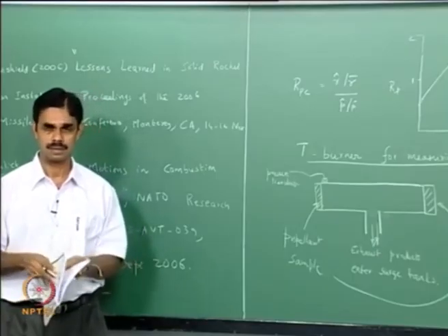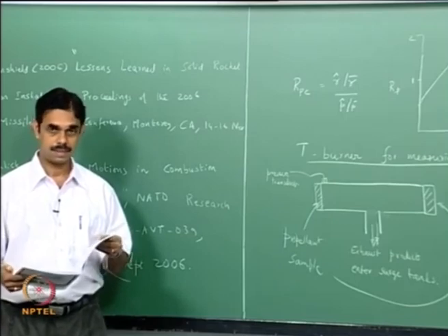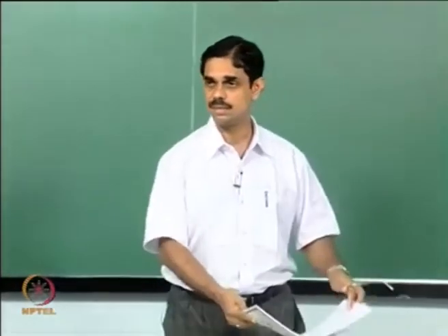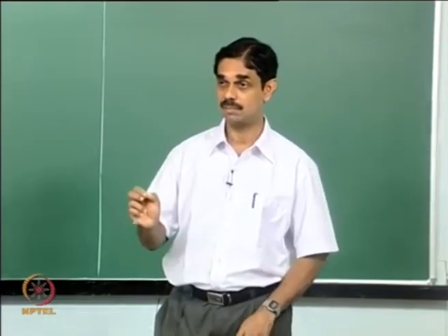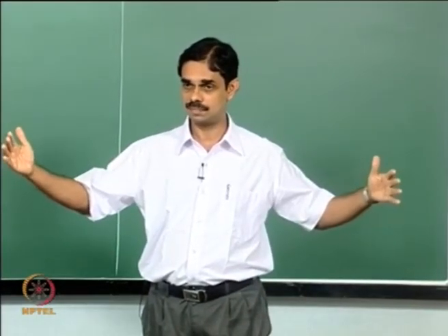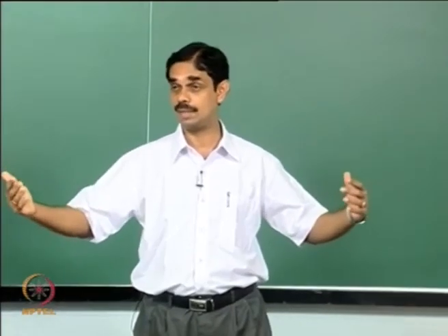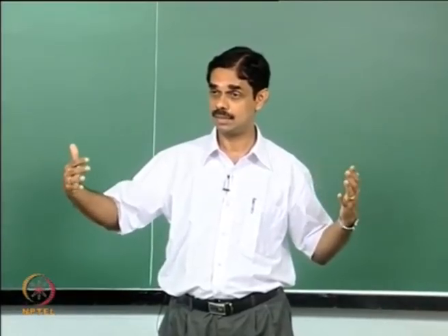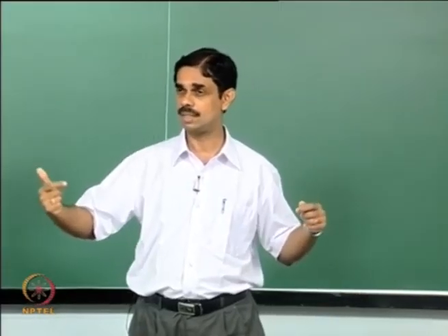Yeah. If you are burning the surface, it will recede, and it won't be a pressure maximum after some time. Why? It will be only receding slightly. The propellant is like a half inch or quarter inch thick sample, so it will recede slightly compared to the length, which is like 1 meter or 60 centimeters or 1.5 meters. The length is determined by the frequency that you want to excite, the natural mode, and so compared to that, a few mm of burning will not change the frequency a lot.